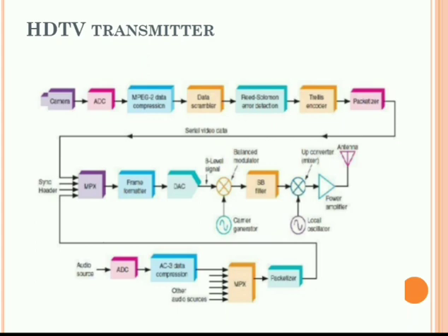The carrier is suppressed here and only the upper sideband is transmitted. Means the carrier is suppressed, the upper sideband of the modulating signal is transmitted plus a small vestige signal, a small portion of the lower sideband, which we simply call a vestige of a signal, that is added to the upper sideband, and both in combination are transmitted after the modulation. This is nothing but vestigial sideband modulation. That is a type of amplitude modulation we are using here.